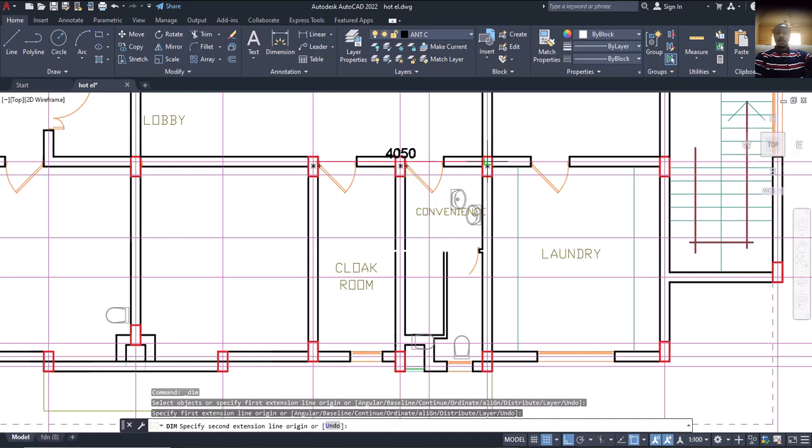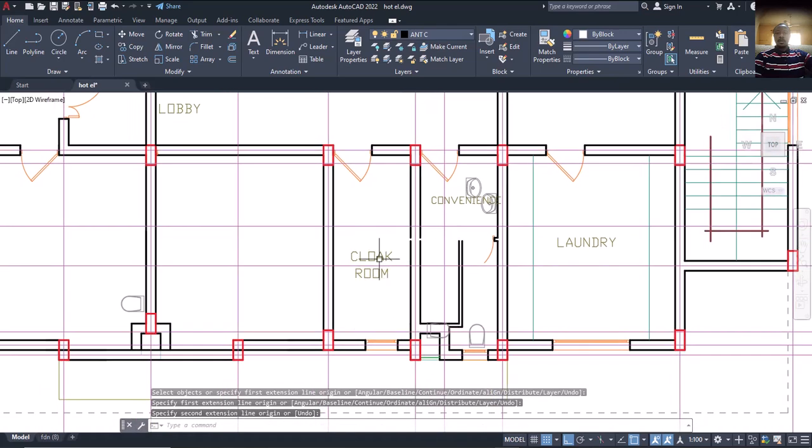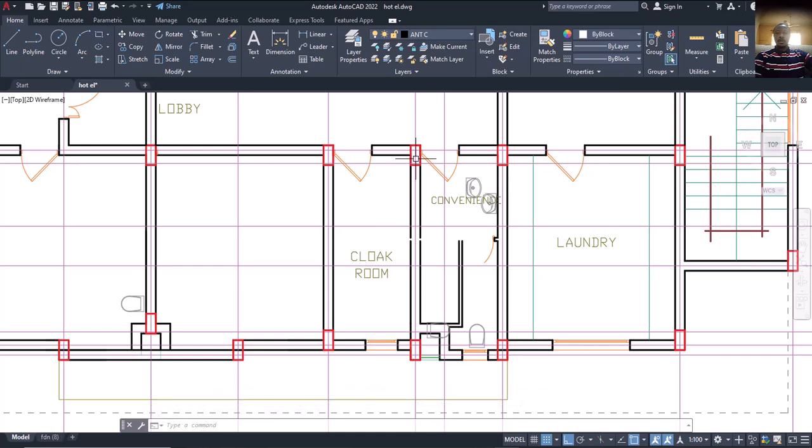From here, this is 4 point something, and from here 4 point something. So which means this place is less than 30 square meters. That means that we can now have a slab, a wall sitting on this slab here, isn't it? So we can have a beam here, from here like this, and also a beam coming here like this.